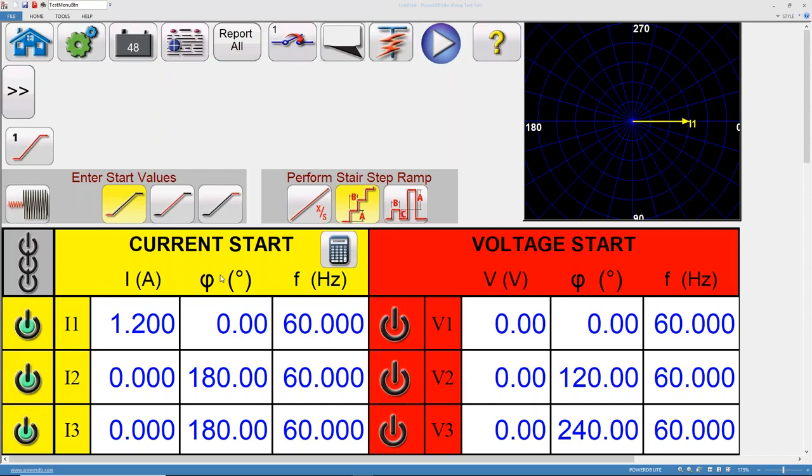We're going to use that pickup value, which in this case is 0.30, and take it times the tap value to give us our values to run our pickups on. We're starting at some value below pickup, and then we're going to ramp into the pickup until the relay operates. So let me get my relay set.